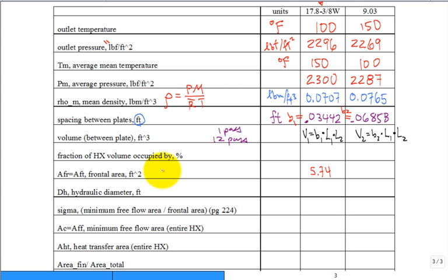You could calculate it by L3 times L2, or you could get it by the number of fluid passages, which is 12, times B1, how wide it is, times the height of it, L2, right? I don't think they're going to give you exactly the same, but they'll be close, because I don't think L3 is consistent. Might be like 5.9.